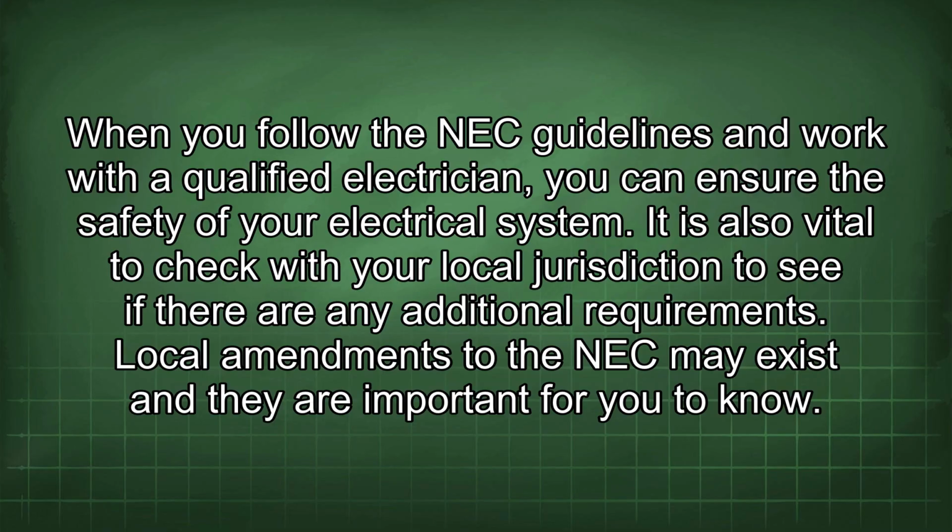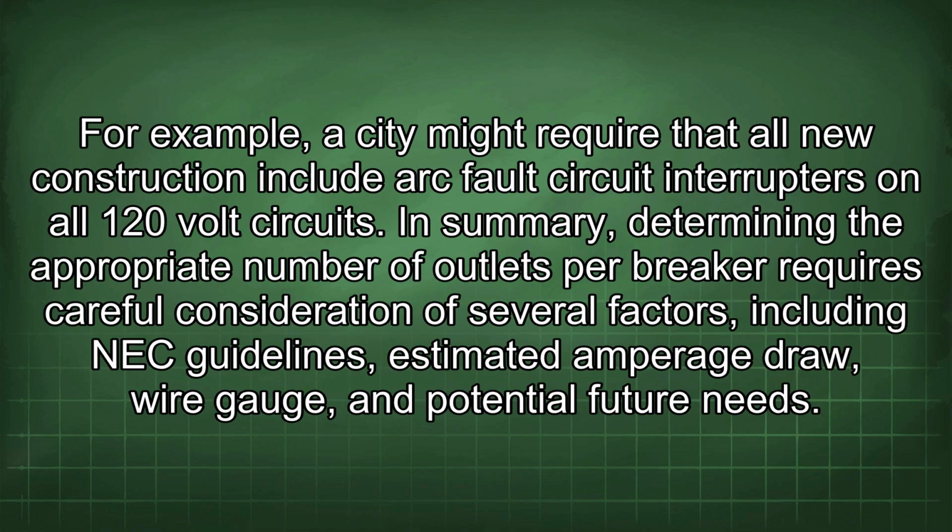Local amendments to the NEC may exist, and they are important for you to know. For example, a city might require that all new construction include arc fault circuit interrupters on all 120-volt circuits.